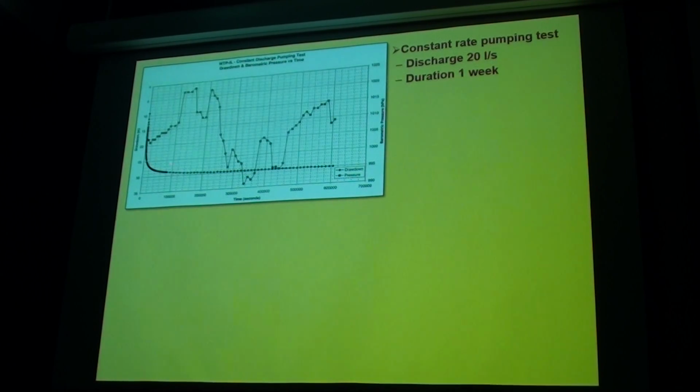Okay. You've got about 30 metres of drawdown in your well. That's quite a lot. As long as you've got a pump that can handle it, it's okay. It may be a little bit inefficient, but either way, you're okay. Everything's going nicely. Okay. Of course, you stop the pump test here, so you don't know if here it's going to go again, but judging by this data, you look like you're doing pretty well, okay, if you get that kind of data.